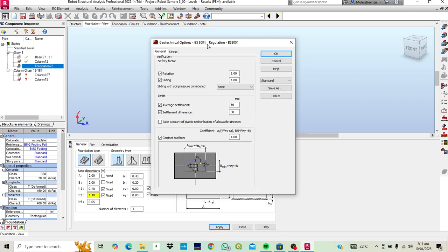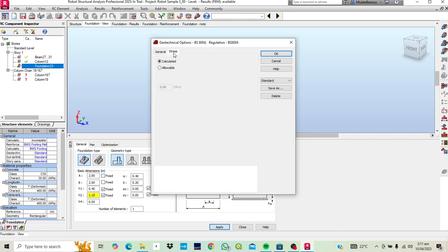This is usually what is done because if you assign fixed connections to your foundations, they're going to have moments and they're going to be more expensive to design. But when they're pinned, they are not carrying any moments. So that's something you should keep in mind. We use pinned connections most of the time, unless otherwise. But for foundations, we use pinned connections.